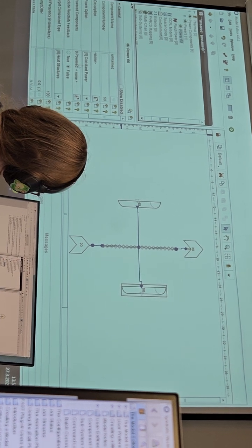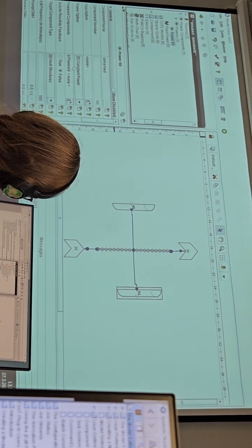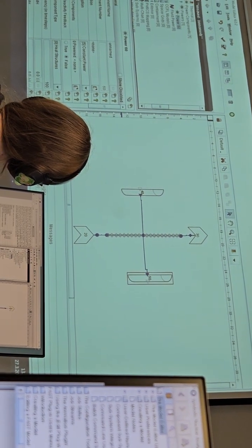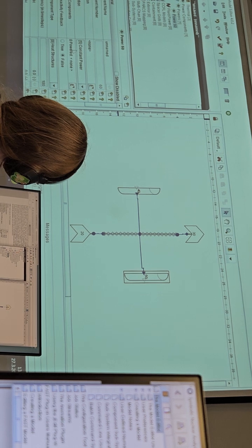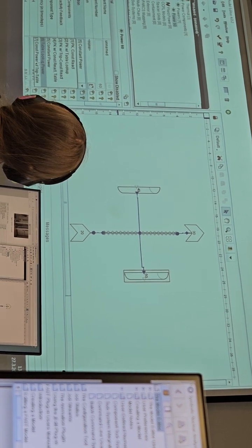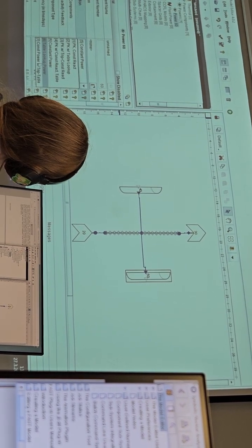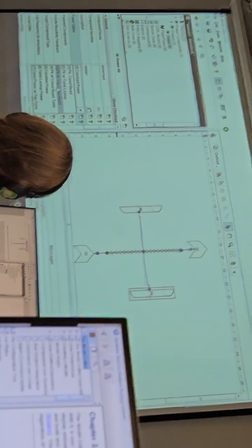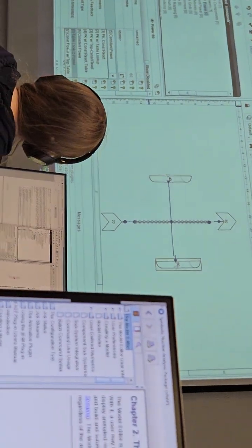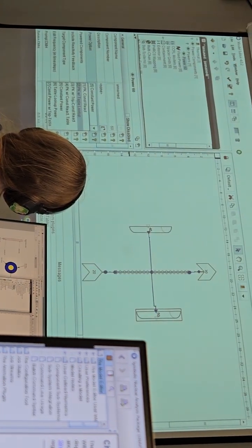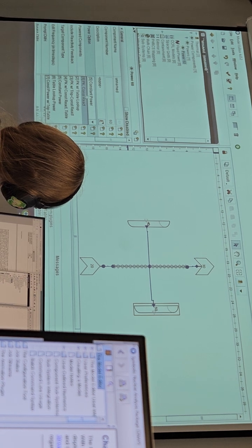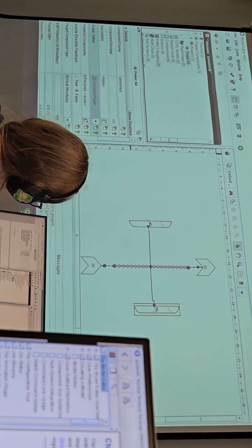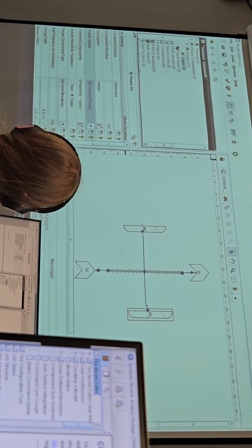In our case, the power option is equal power. Sometimes when you need to simulate a reactor core, you need to make a kind of realistic behavior. It will be like table lookup power, when you calculate the reactivity coefficients and change the power manually, for like investigation of the step change and so on, and all other options. There are also options for the reactivity coefficients, but it has to be modified in the root folder of TRACE to see these options. But still, we need to choose the powered components.